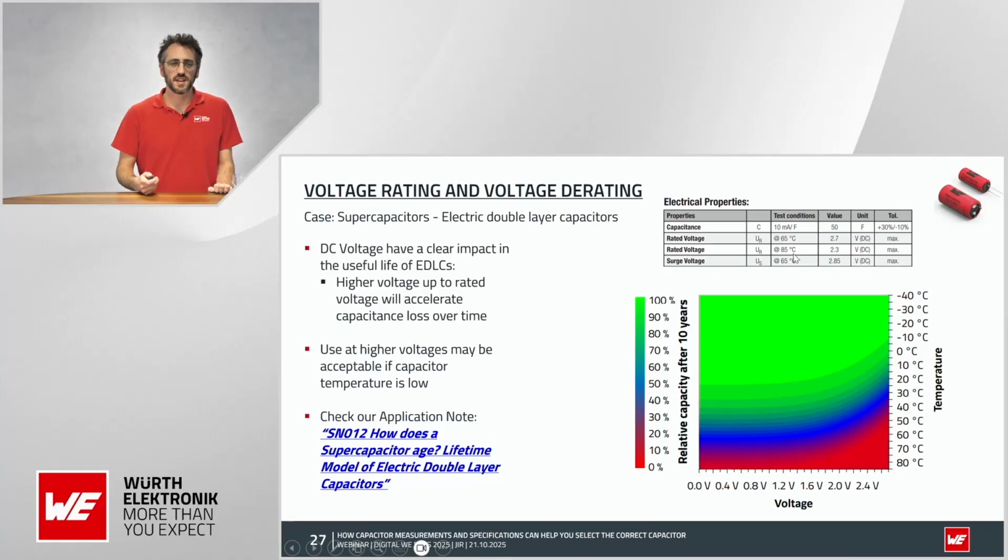But you have to understand high voltage will accelerate the degradation of the electrolytic, of the oxide, of the dielectric layer, and you will lose capacitance over time.